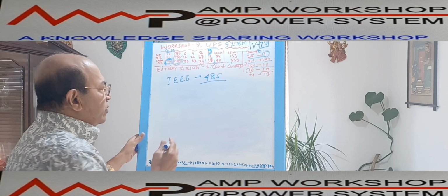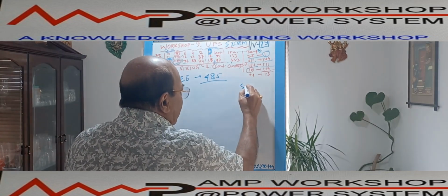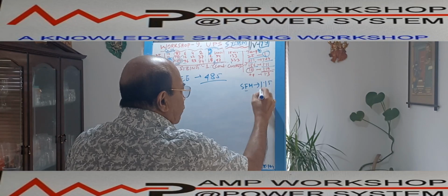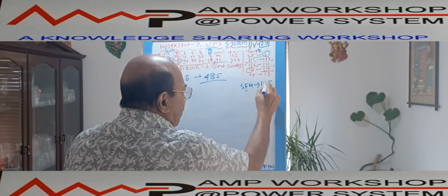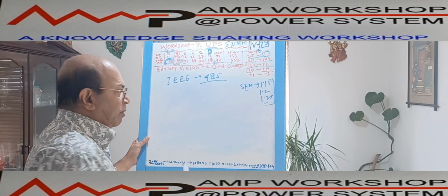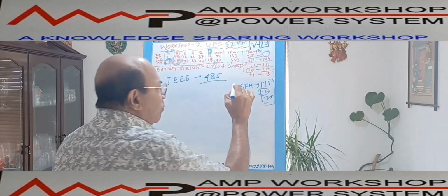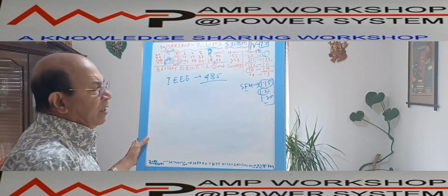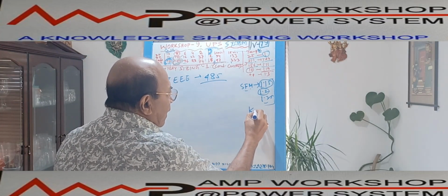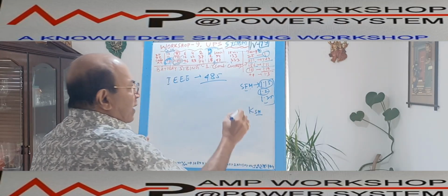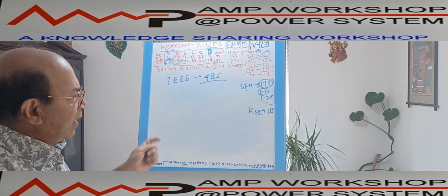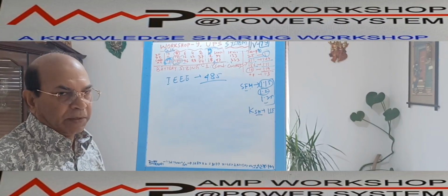So there will be one factor we call the safety margin of the battery. The safety margin could be 1.15, 1.2, or 1.25, depending on the design engineer and the parties involved, after discussion. Presently, suppose we consider 1.15 as the safety margin we need. This is one of the factors, the safety margin, KSM, that we are considering as 1.15 for the battery sizing, and the UPS also has a 15% margin. That is one of the points.